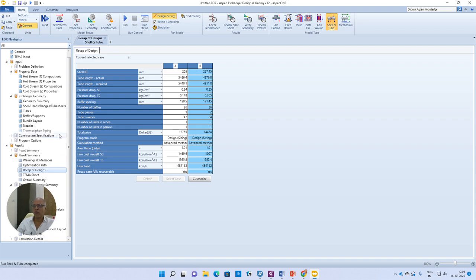As I said, this is quite capable. You can go into each of these details, and depending on your requirement, you should be in a position to deal with an appropriate design. Start with probably the default values taken by the simulator, and depending on your requirement, one by one, try to change and see what its effect is on the cost and also on the design. And you will be in a position to develop the required drawings, present all the design data in the form of a particular template, which can be passed on to maybe a fabricator, get this equipment fabricated and installed.